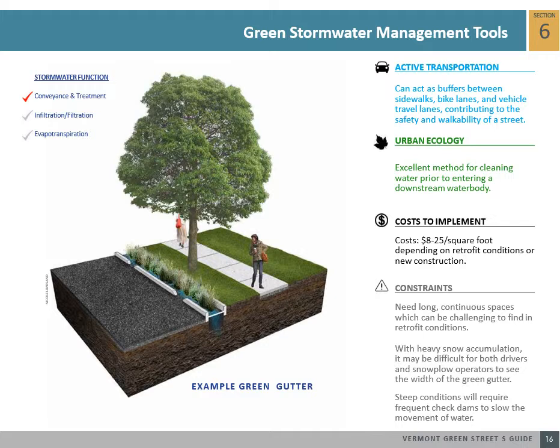Rain gardens retain stormwater, attenuating peak flows and reducing overall stormwater volume. They can also allow for infiltration, depending on the capacity of the native soil. Although rain gardens can share certain characteristics with swales, their primary function is to maximize stormwater storage and infiltration, not conveyance to another location. As a result, they are located where they can collect and treat stormwater from adjacent impervious surfaces. Their versatility in size and shape make rain gardens a flexible option for application in space-constrained downtown areas.